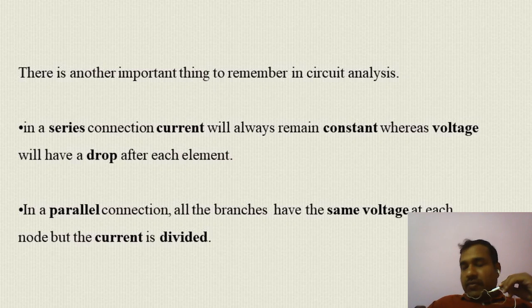Now one more important thing you should know, you already studied this: in a series circuit, current is the same through all the elements but the voltage drop across each element is different. Similarly, in the parallel connection, voltage across each element is the same, but current will be divided among them.